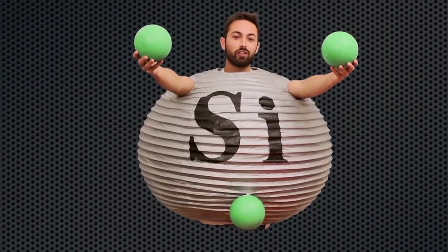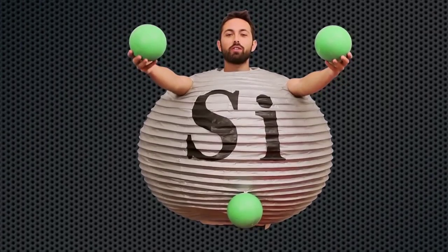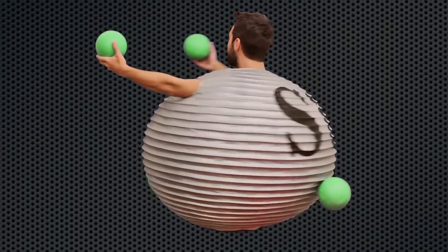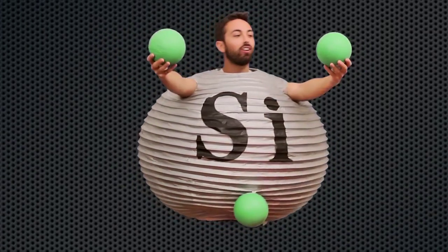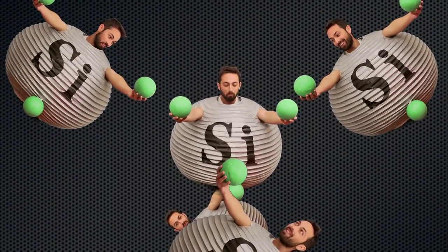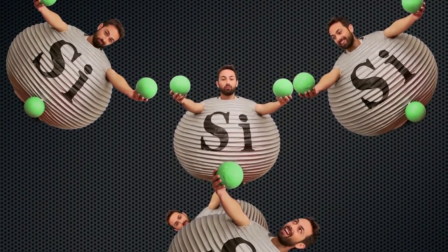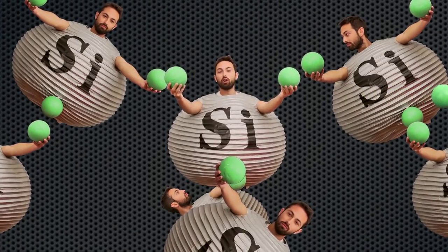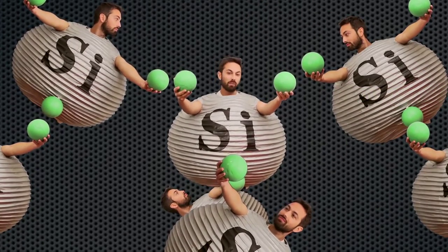Pure silicon is a semiconductor, which means it conducts electric current better than insulators, but not as well as metals. This is because an atom of silicon has 4 electrons in its outermost or valence shell, and this allows it to form bonds with its 4 nearest neighbors. So it forms a tetrahedral crystal. But since all these electrons are stuck in bonds, few ever get enough energy to escape their bonds and travel through the lattice. So having a small number of mobile charges is what makes silicon a semiconductor.